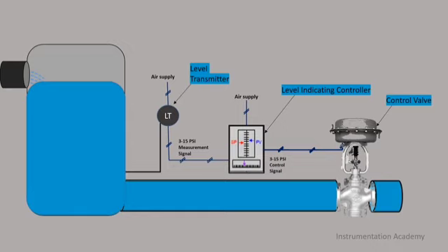When the controller is placed in the automatic mode, it will move the control valve to whatever position it needs to be in order to maintain a constant water level in the tank. A human operator running this tank has the option of placing the controller into manual mode. In this mode, the control valve position is under direct control of the human operator and it is his responsibility to move the control valve to the appropriate position to hold the water level at the set point.